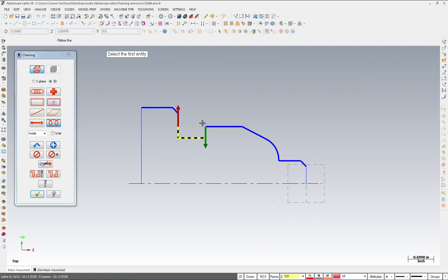So I'm only grabbing this groove, and I'm only machining out this groove. I'm not worrying about this other outer diameter right here. I'm actually just grabbing the inside here by selecting partial. So partial will allow you to grab two different lines, and then based on everything in between those lines, you'll machine them out.